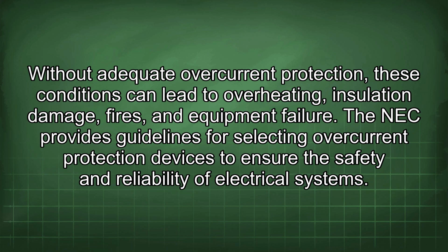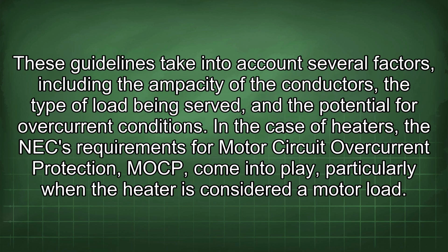The NEC provides guidelines for selecting overcurrent protection devices to ensure the safety and reliability of electrical systems. These guidelines take into account several factors, including the ampacity of the conductors, the type of load being served, and the potential for overcurrent conditions. In the case of heaters, the NEC requirements for motor circuit overcurrent protection come into play, particularly when the heater is considered a motor load.